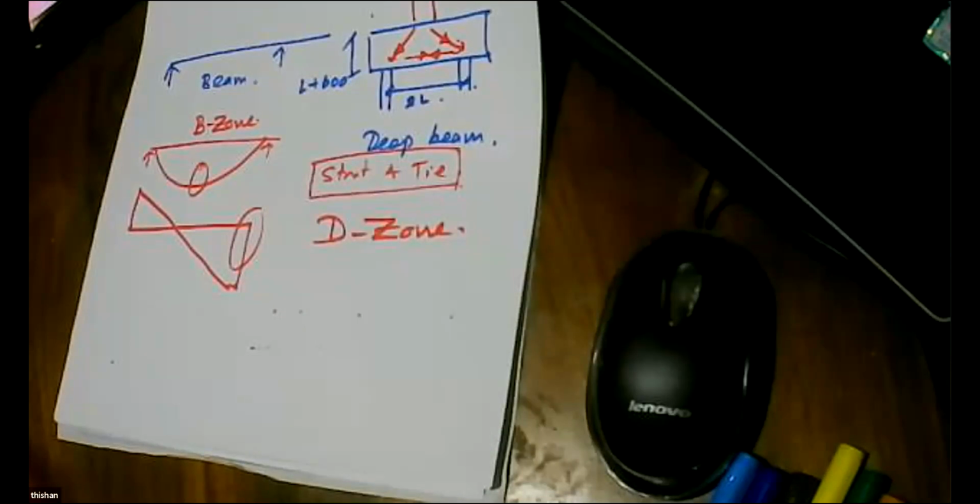the theories that we are deriving here are applicable only when the flexure dominates. Flexure dominates, right? Not the shear dominates. Flexure is the one that is going to fail. The beam is going to fail in flexure, not in shear. So that's where we have to be a little concerned.